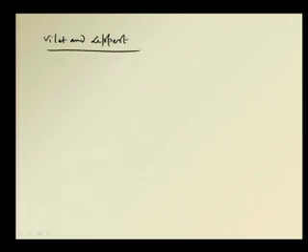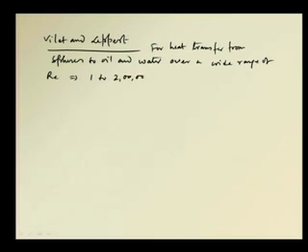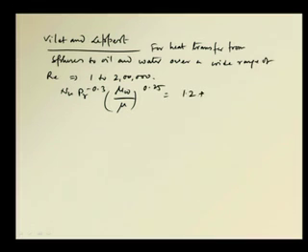And then two more relationships, by Vliet and Leppert. They said that for heat transfer from spheres to oil and water over a wide range of Reynolds number, 1 to 2 lakhs, Nu times Prandtl to the power minus 0.3 times (mu w by mu) to the power 0.25 is equal to 1.2 plus 0.53 Re_D to the power 0.54.